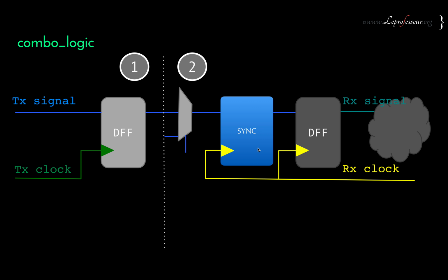Means that the synchronizer will go very frequently into the metastable state, which is not good for the overall chip. So that increases the probability of failure, or the MTBF number gets affected exponentially.